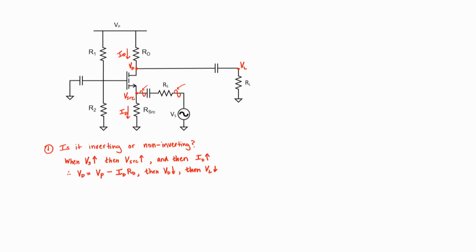The flaw in the derivation comes when I identified this drain current and this drain current as the same. Let's label it in the circuit diagram. Is this drain current really the same as this drain current? No, it's not. It's not because we have some AC components of the drain current going out to the load resistor, and we have another component of the drain current entering from the signal.